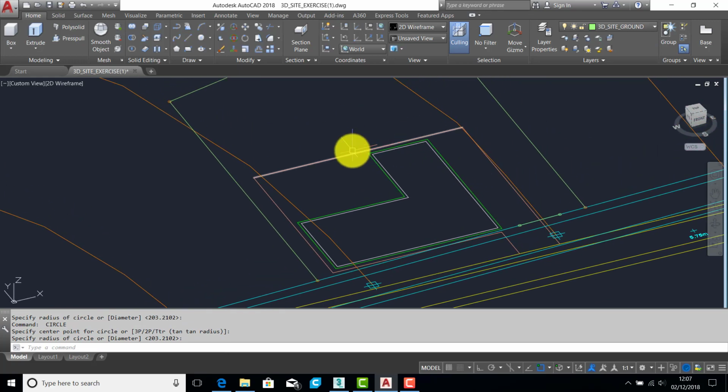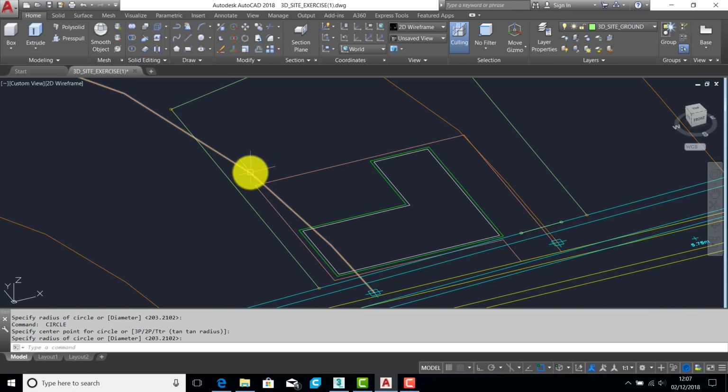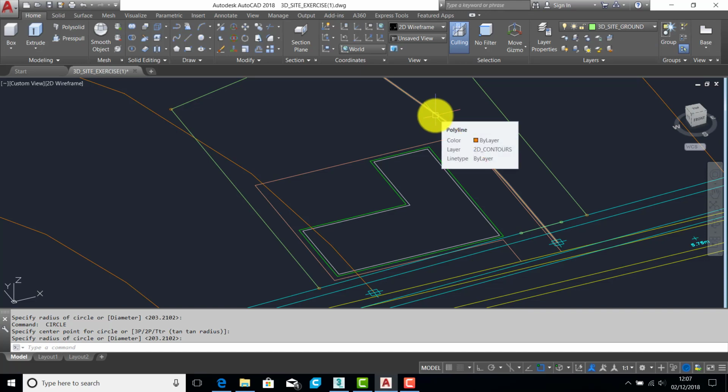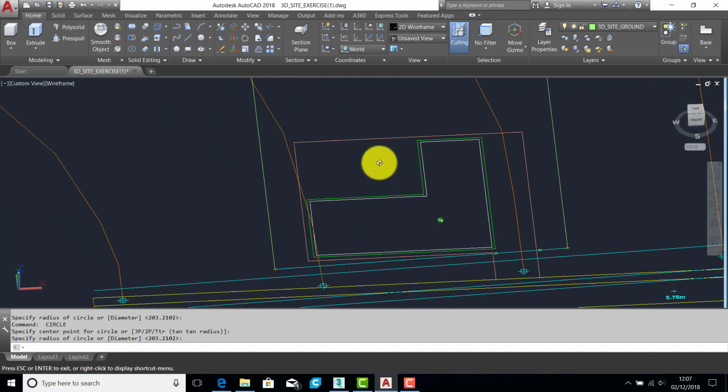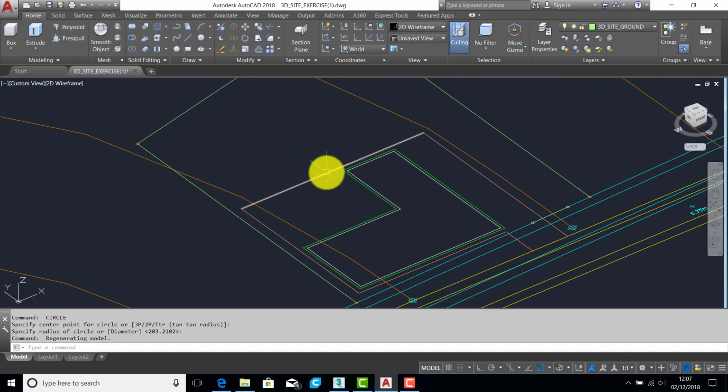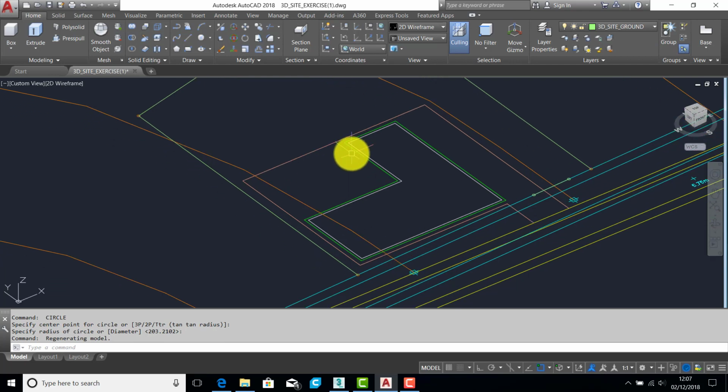And for this site, we're saying that it's a flat site. So we'd basically be choosing a level ourselves. We don't want to cut too much material out. We don't want to add too much material. So a height in between these two contours is most likely to be the sensible choice. So if we said that the site itself was at a height of 3.5 meters, that should work pretty okay.